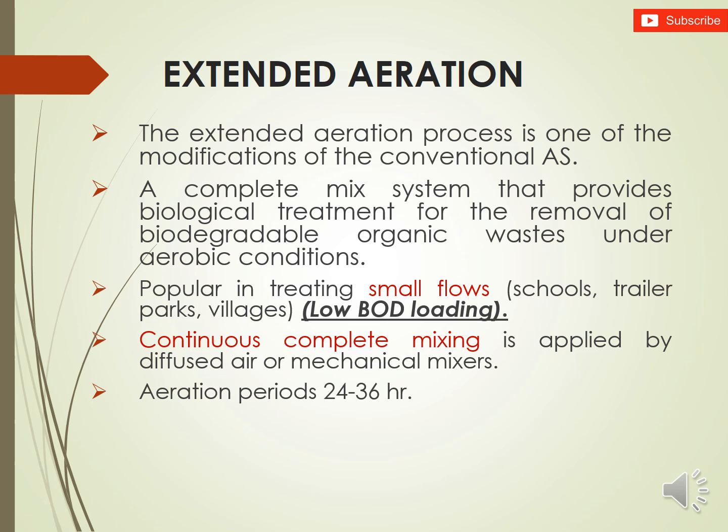And here, because the flow is small and the BOD is low, we apply longer aeration periods, and this will result in the excluding of the primary treatment stage. Why? Because there is a small amount of sludge compared to the conventional or high flow treatment plants. So there is no need to apply a primary treatment stage.